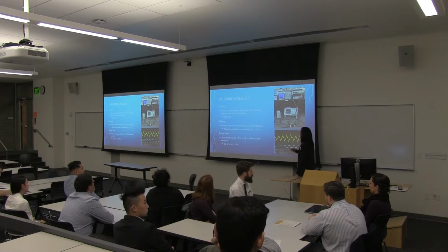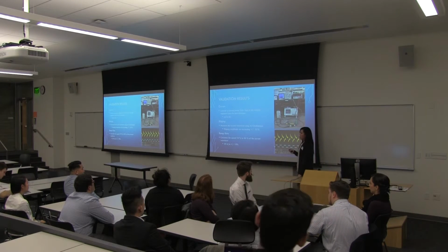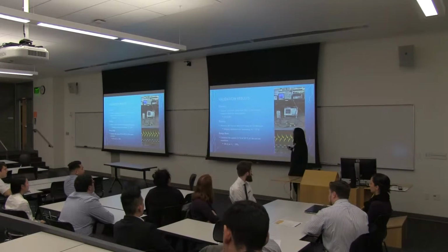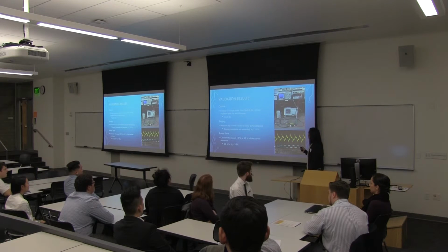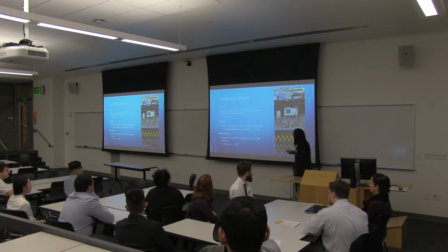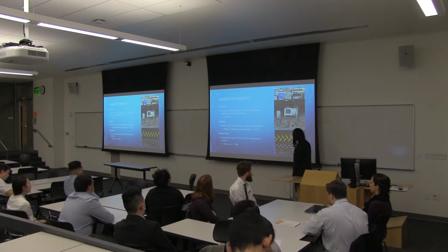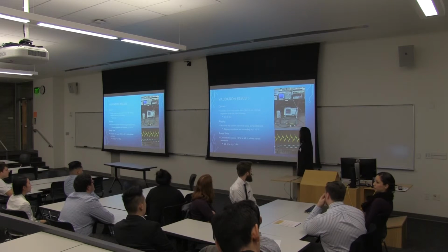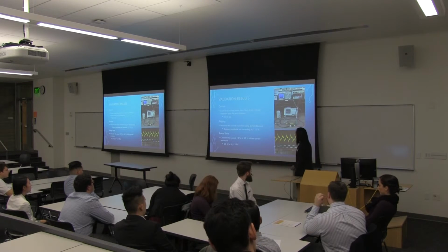We verified our mini slammer design using a test suite code provided and designed by Intel Corporation, and this is in a figure here. This is how we set up in the lab to measure the current. We measure the current by connecting a current probe between the Vout of the voltage regulator and the mini slammer. Our current measurement was 6 amps DC.